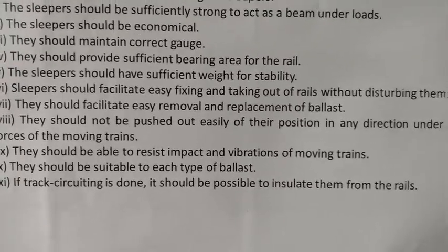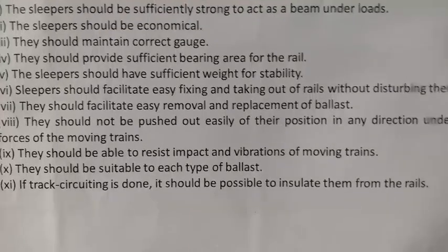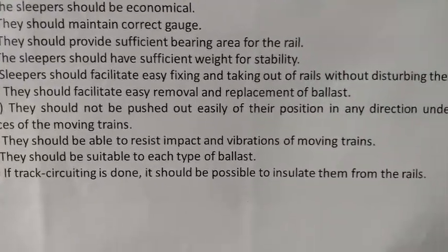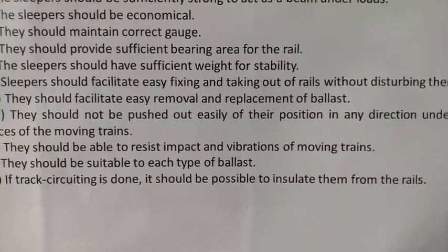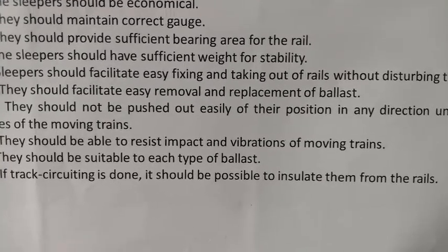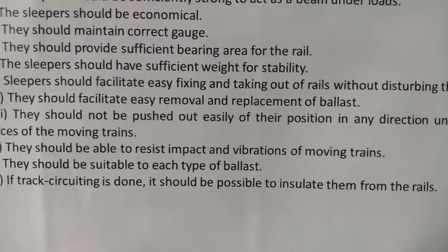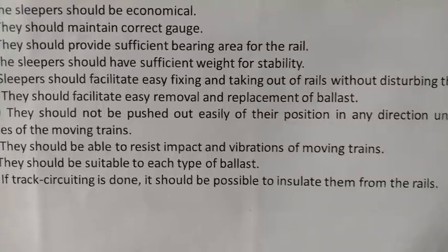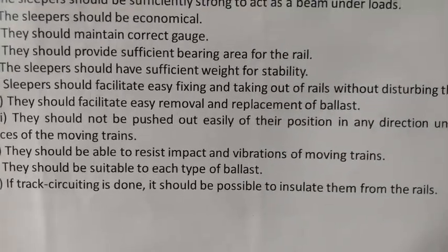See, not only the sleepers we are talking about, we are also talking about the ballast that is beneath the sleeper. They should facilitate easy removal and replacement of ballast. Whenever we feel the ballast is more in quantity or we need to reduce that amount, we will just remove it.